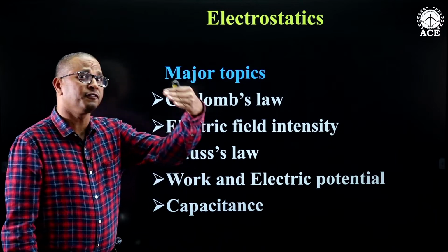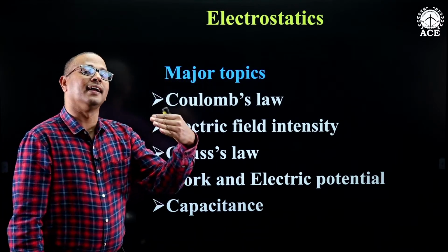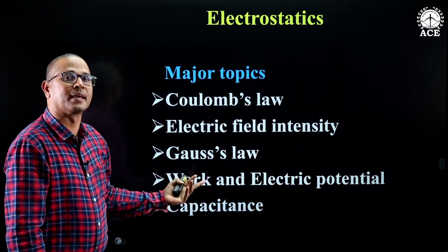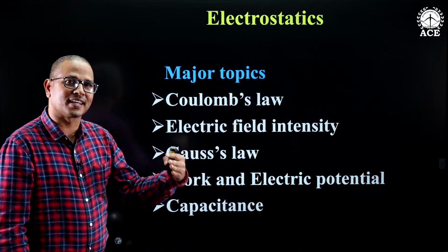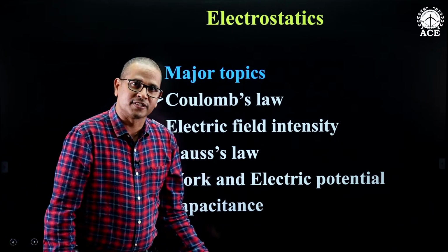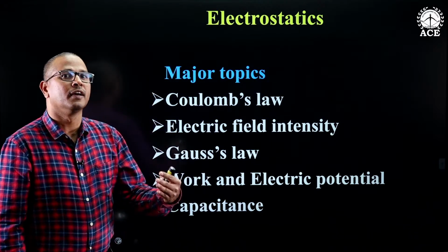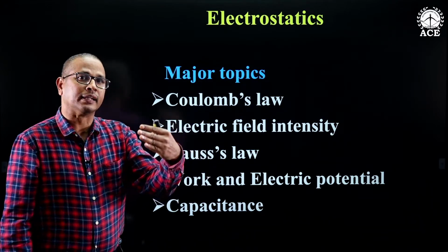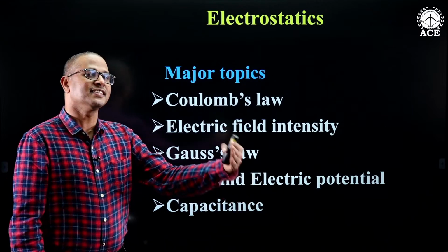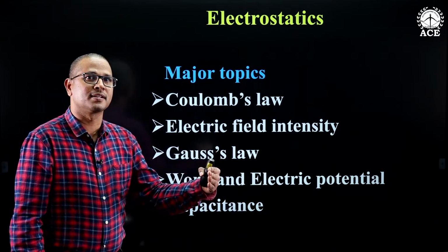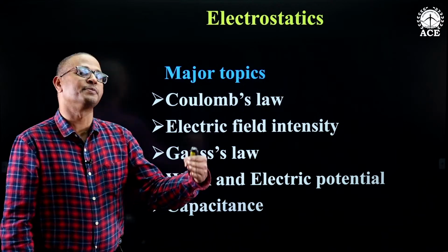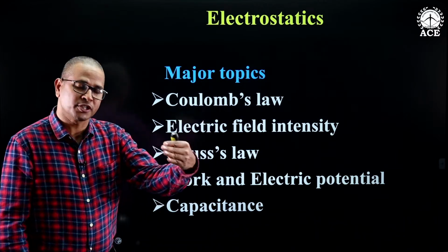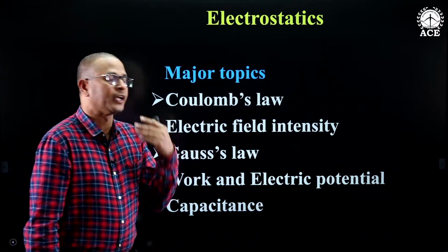With the help of analysis of electric field and electric flux density, we have one application, which is an electrical device called capacitor. Capacitor is an electrical device capable of storing energy by means of electric field, which is half CV square in the form of potential. In circuit theory, we have half CV square, under lumped parameters. Whereas in field theory, we have distributed parameters, epsilon and E. Epsilon is measured in farad per meter, whereas V is measured in volt. Electric field intensity is measured in volt per meter, field strength per unit length.